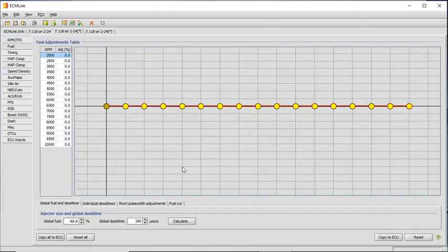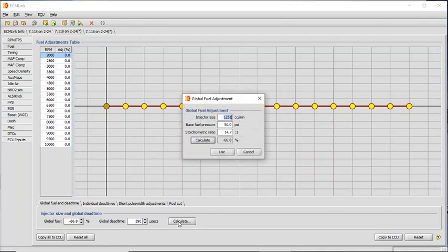Okay. Fuel, this is an obvious one. Car's not going to run without fuel. If you don't know that by now, step away from the keyboard. So aside from that, we want to put in our correct global settings as far as your injector size. Now, the injector size may or may not match the actual injectors you have. I've discussed that in other videos, but if you're with a mass airflow sensor, it might be a good idea just to set the actual injector size that you have or get as close to it.